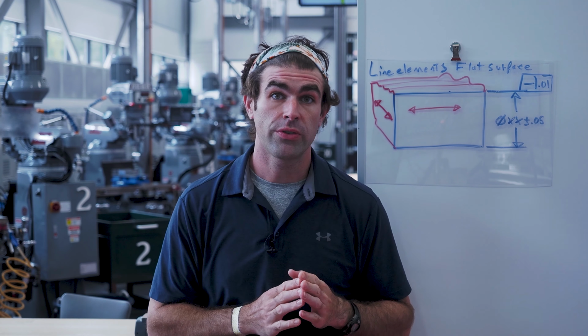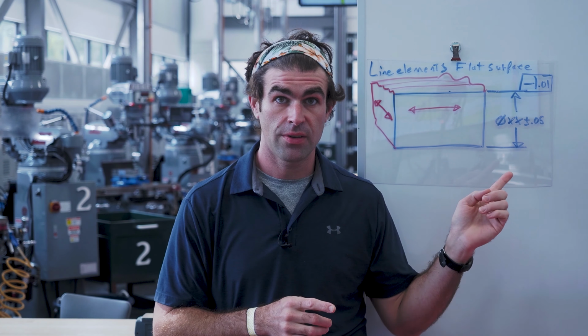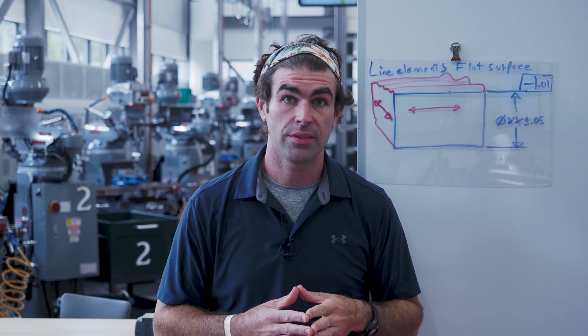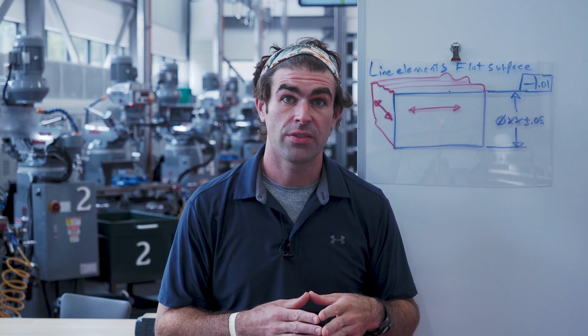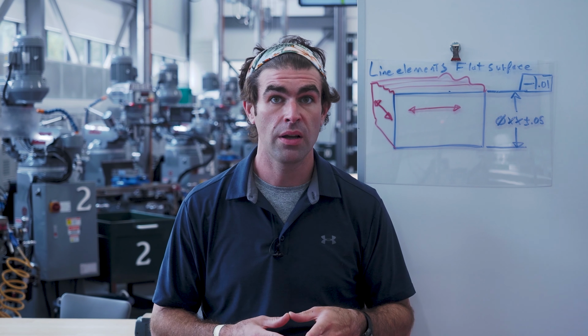So in this use, the straightness tolerance is required to be less than the size tolerance. It wouldn't make sense for the straightness tolerance to be greater because you'd be violating MMC, the boundary of perfect form.